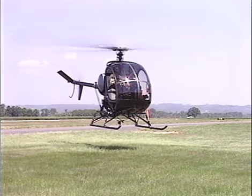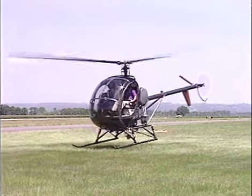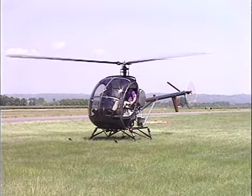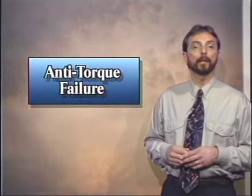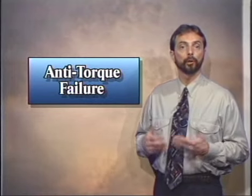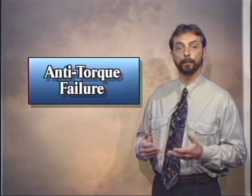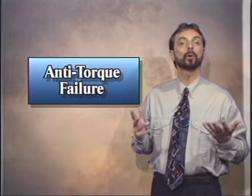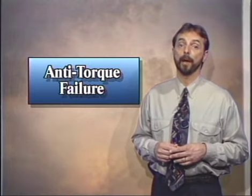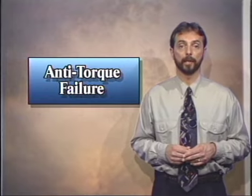The torque reaction produced by the relatively high power setting will create a turning motion to the right that builds up rapidly. Close the throttle immediately without varying the collective pitch position to eliminate this turning effect. If the helicopter is allowed to spin much past 90 degrees, the torque effect will become so great that you'll lose control of the aircraft. From this point, follow the procedure for a hovering autorotation.